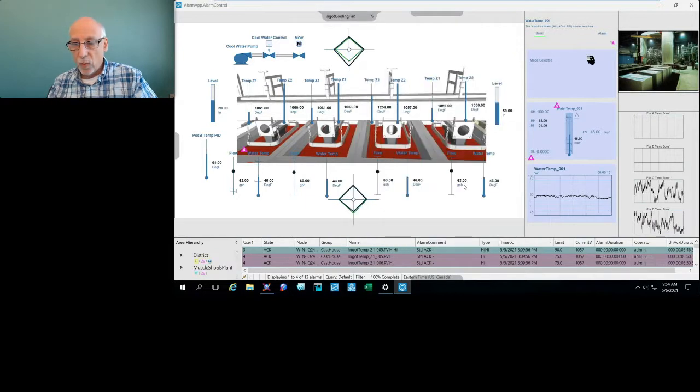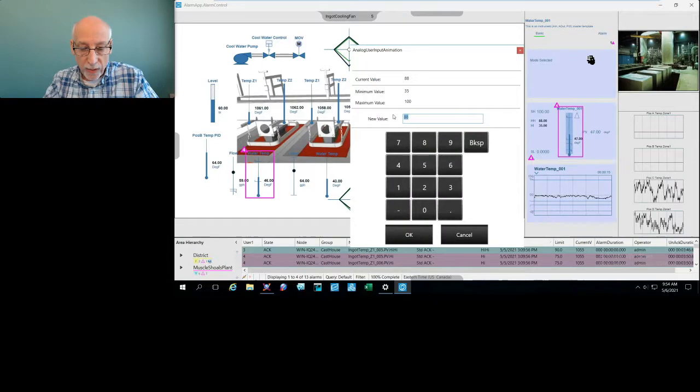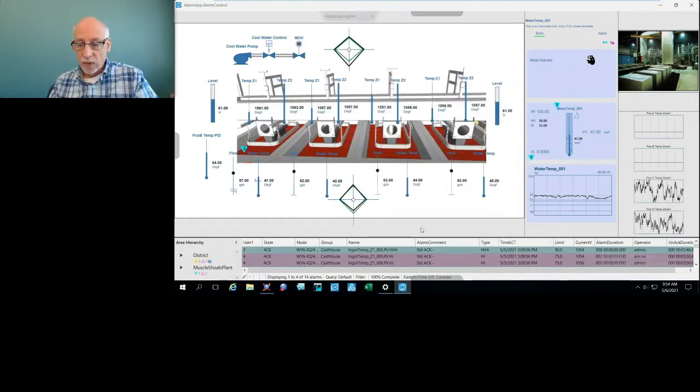And you can see, built into these faceplates is something called that alarm border animation. So it's showing up on my faceplate. It shows up on where my asset is on the actual screen. So it really is going to get the operator's attention when that condition occurs. I'll set that to a high alarm here. Let's put that at, say, 38. And that's a different level of alarm, so that's showing a different color and showing that alarm border animation at a different level.